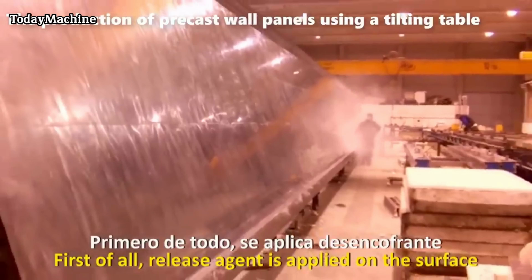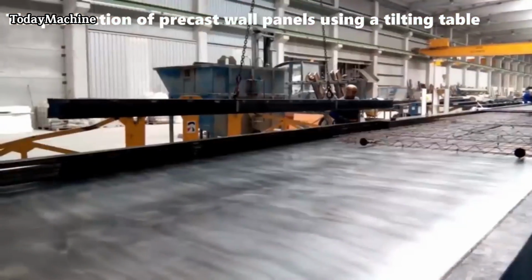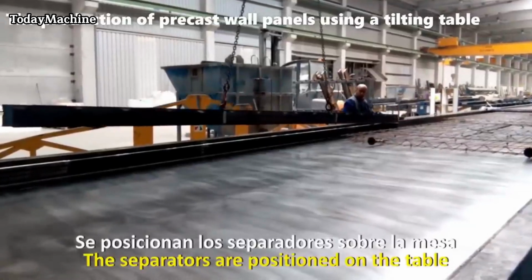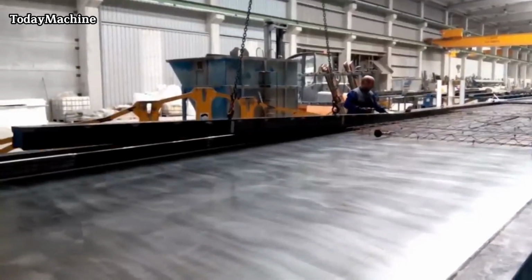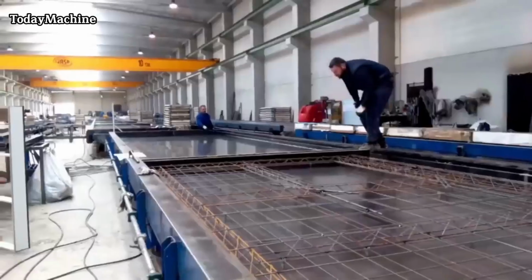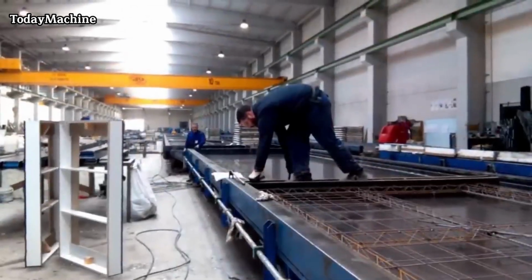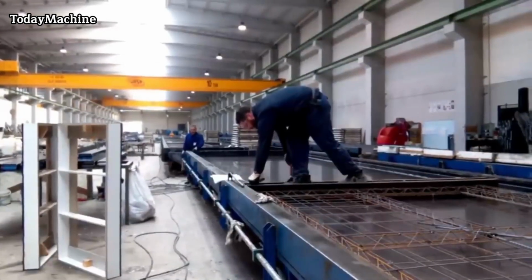The manufacturing process begins with the application of a release agent on the surface of the tilting table. A release agent is a substance applied to the mold or formwork to prevent the concrete from adhering to it. This step is crucial to ensure that the finished panels can be easily removed from the mold without damage. The release agent creates a barrier between the concrete and the mold, allowing for clean and smooth panel surfaces.